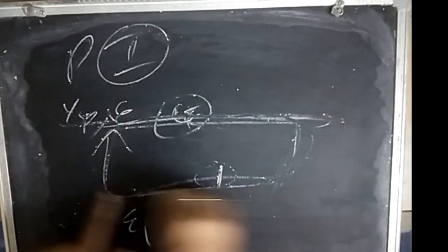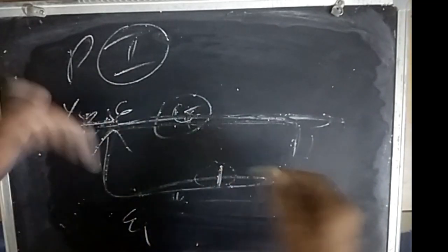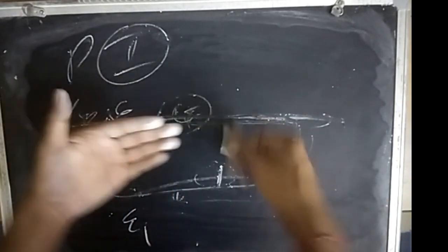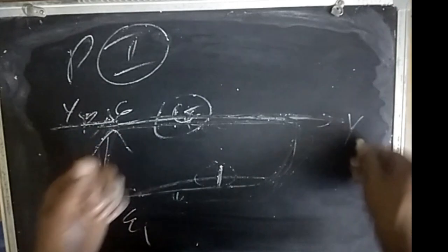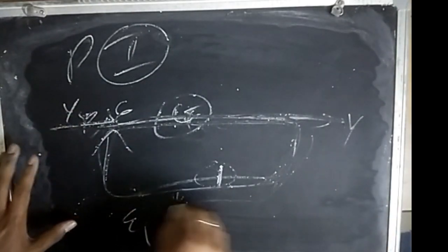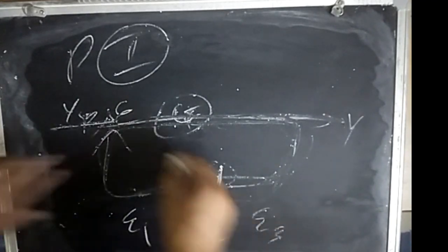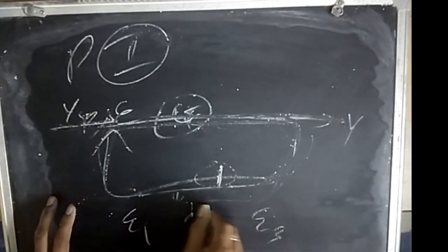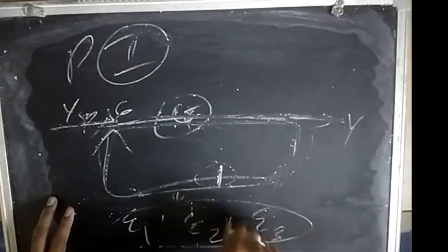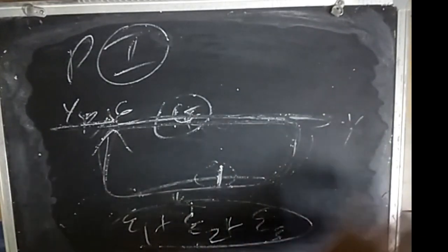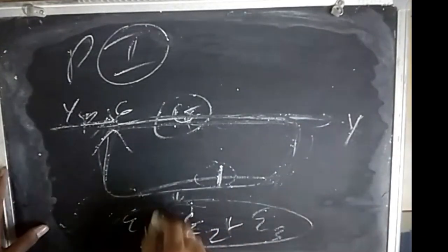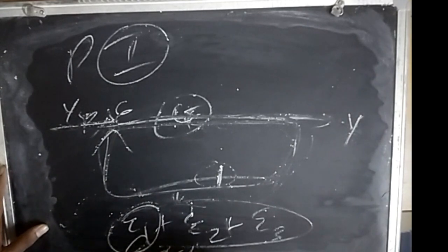In the next run, we again run this. YSP has changed, and we are trying to achieve this Y, so there is again some error. What will happen? The integral will integrate all this error and take it into account, so the past error will also be there. Just remember this.